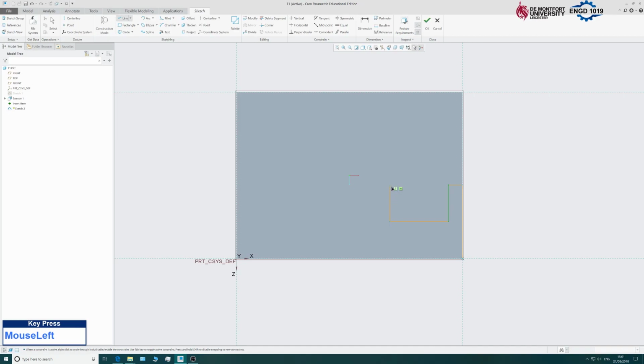And if we look at the drawing, that is actually what we need, so I'm going to accept that. So you just accept that by left clicking. So another horizontal line. Look, you can see here when I snap to a certain point, it makes the line equal to that line. I don't actually want that, so I'm just going to avoid that snapping.